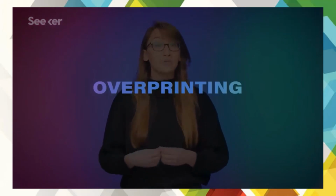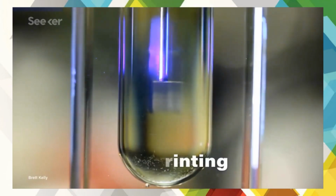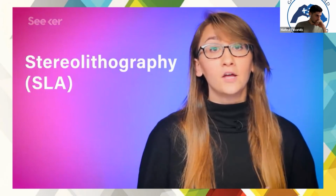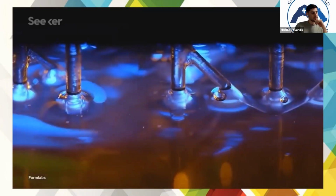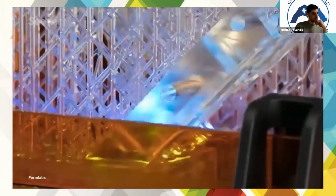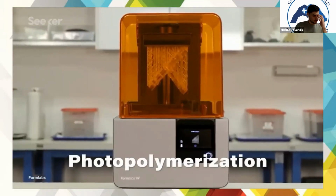Another promising feature of this device is called overprinting, which is when they can take objects and print around them, like taking the metal component of a screwdriver and printing the handle. This is a technique that our additive manufacturing printers today have trouble accomplishing. You see, even other liquid printers, like those that use stereolithography, are not considered volumetric. Although stereolithography printers also use a bath of resin, they're still printing objects layer by layer, slowly pulling the object out and selectively curing sections with a light in a process called photopolymerization. Researchers for CAL eliminated this long process, since CAL can print within minutes and is special since it can print all at once too, and it's still a very new technology.